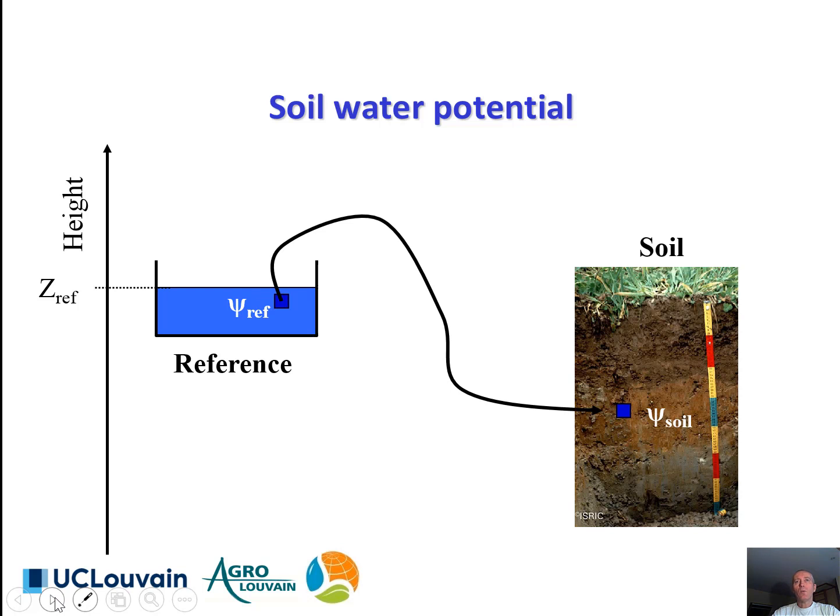The pores will therefore be small, and capillarity will develop in the soil system. In such cases, the water flow velocities will be rather small, and as a consequence, the kinetic energy component of the total energy of a water particle in a soil will be small, and we can concentrate on the potential energy components to describe the energy of the water particle.